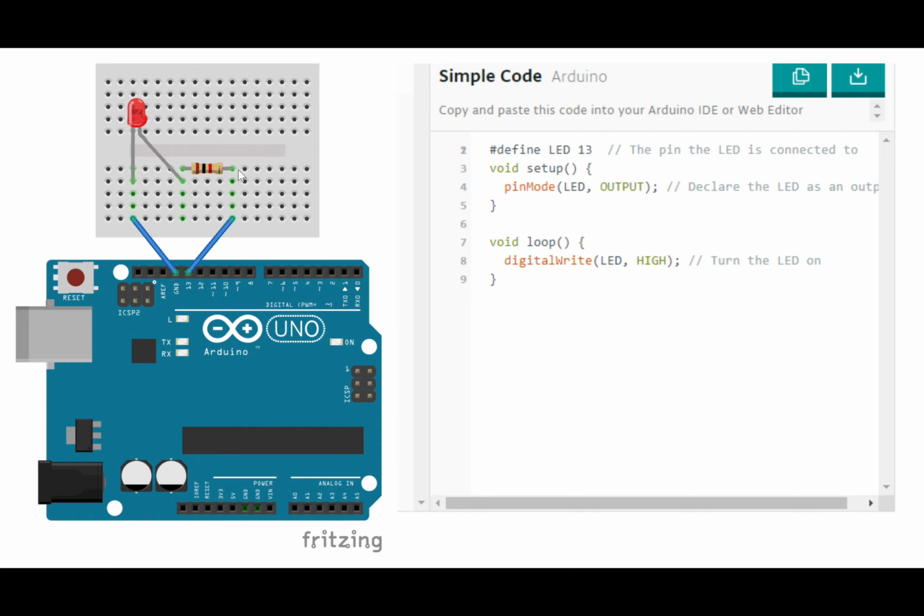So it shows these little green circles. This resistor is technically connected all the way down to this wire, and the other side is separated. So these 2 sides are separated. The wire is not interfering with any of these holes here. And the holes work similar to the pins on the Arduino. You just plug things into them. So it goes into a resistor. Notice the resistor is before the LED, because if this wire somehow accidentally went here, it would fry it. It would probably supply too much power, and the LED would have a bad time with that.